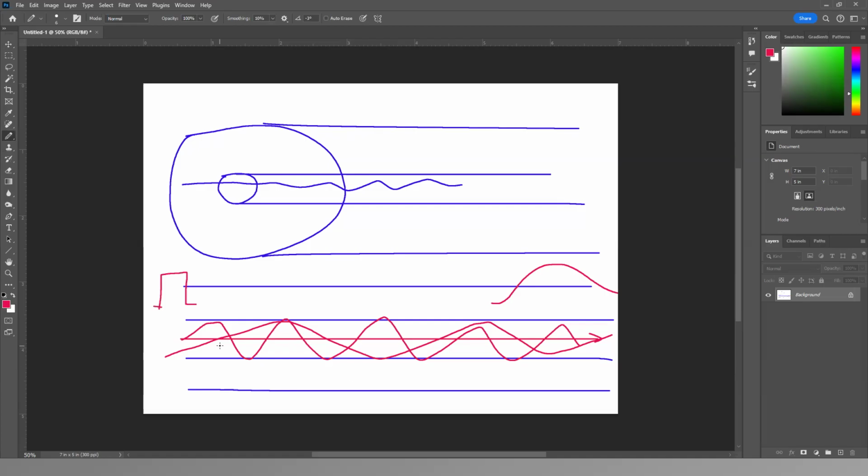So what happens is that graded index is implemented. If it's a graded index fiber, the core in the middle is constructed a little bit differently. The core is not consistent. In the middle, the core will have the greatest index of refraction to slow things down, because if you slow that down and let the others catch up at the destination, then you're going to end up with a sharper pulse at the other end.